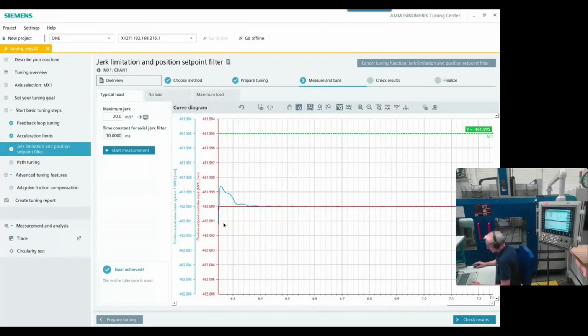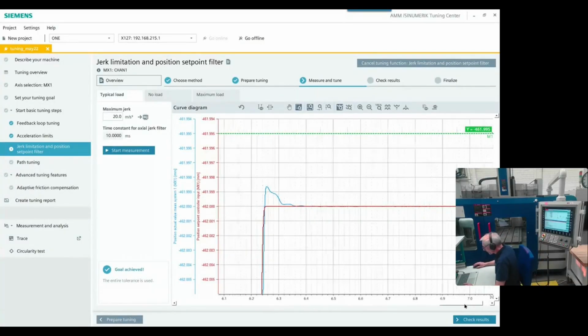And then you will see that, yeah, the vibration is gone. There is a small overshoot of about 1.5 microns, which in my opinion is acceptable. And so that's the trade-off you have to find yourself. How low of a jerk do you really require? And for that, I think you need to get some experience with various axes, small axes and big axes, and then you will have more of a feeling of what kind of behavior is suitable for that kind of axis.